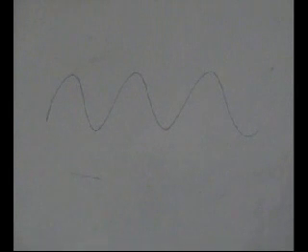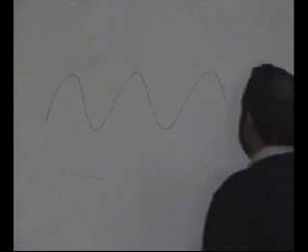Let's say it's an ECG machine, and it is somehow picking up this 50 Hz signal, and it's just corrupting all my values, and I want you to design a system which can take away this signal. So it's not an easy question to ask or solution to make. You need to really use techniques which we will be learning in this course, how to take away a sinusoid from a signal, how to take away an entire band.